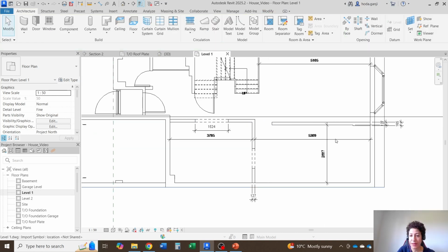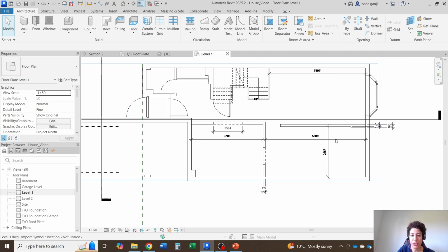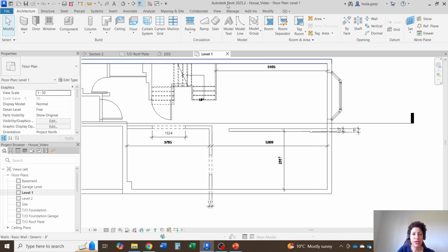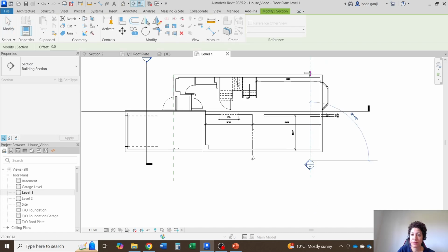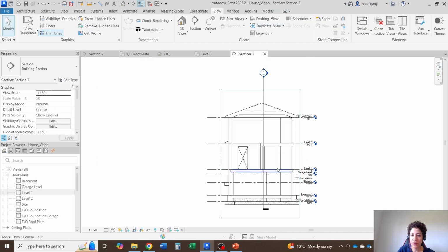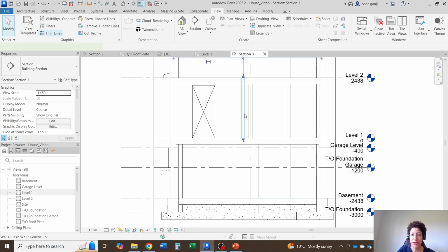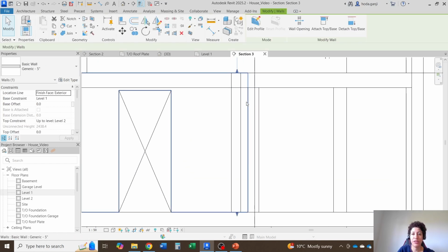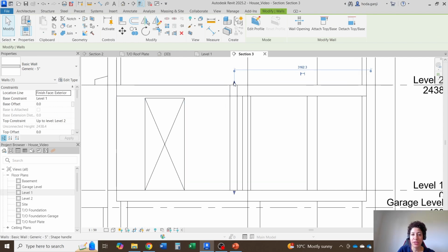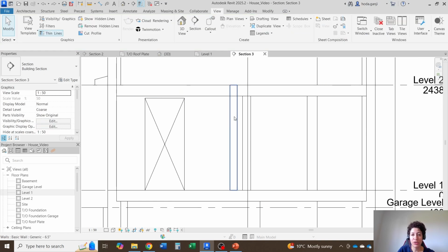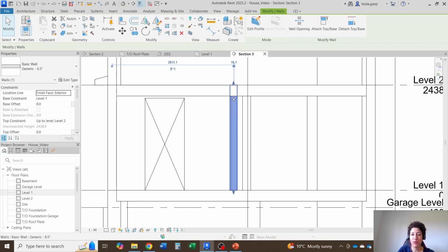There we go. And another thing I wanted to mention, if I draw another section somewhere around here, for your interior walls, let's say this one, and your other interior walls, they don't go all the way up, but they just finish right below the floor. Okay, so you should either grab it and move it down by the shape handle. That's one way to do it.